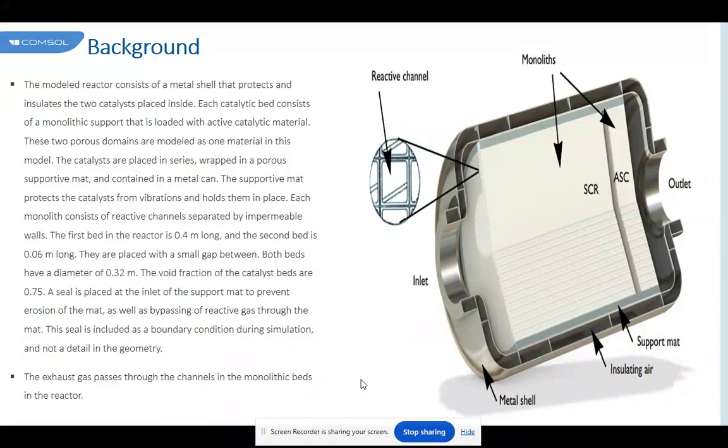The fluid strongly prefers passing through the section with the lowest back pressure regardless of its placement, core or ring, or periphery of the substrate. In this paper and simulation, the two cell densities used differed by approximately 40% in their apparent permeability, which is sufficient to impact significantly the fluid distribution. It is recommended to explore other combinations with a more similar apparent permeability by varying the channel size, wall thickness, or amount of washcoat.